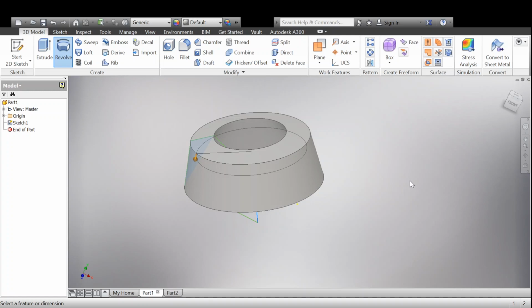You know when you use a lathe to make a baseball bat? A baseball bat is made out of stock wood. It's literally rectangular solid wood. They put it on a thing, it spins, and they take a cutter and move the cutter to cut away and shape the bat itself as it revolves. We can do that in this feature by choosing this option here, which we're going to do in a couple of lessons. That would remove whatever exists already from the current solid, instead of adding or building that solid.